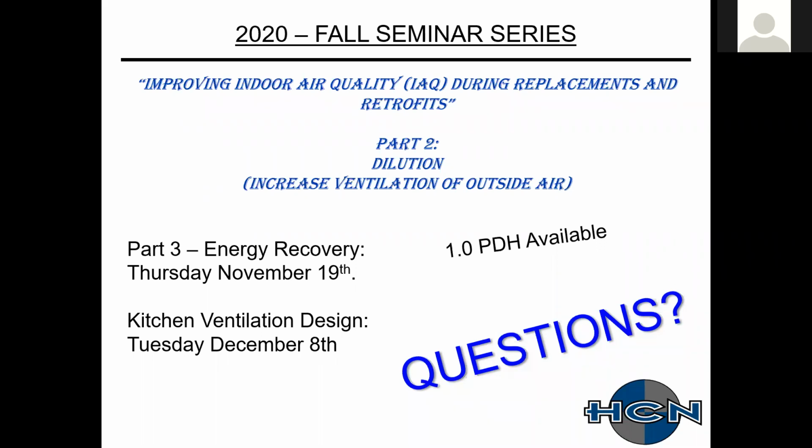On the high end, I would think that your outside air is still considered to be too warm or too moist to really change that. On the opposite side, where colder air, if you have more outside air, it depends on your internal cooling loads, but with the increase of outside air, you might have a situation where before you would be able to provide free cooling with 40-degree air. Maybe with the higher outside air, you therefore would be able to provide free cooling with 35-degree air.